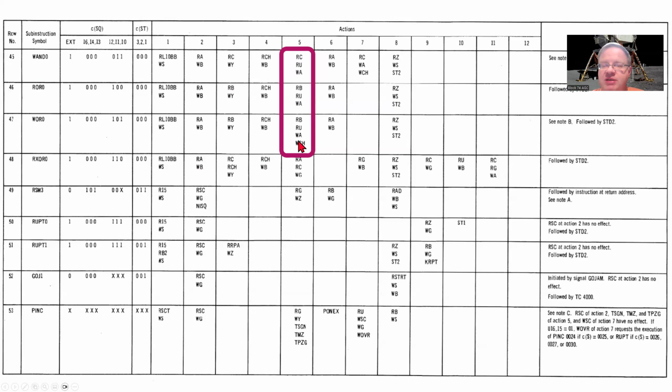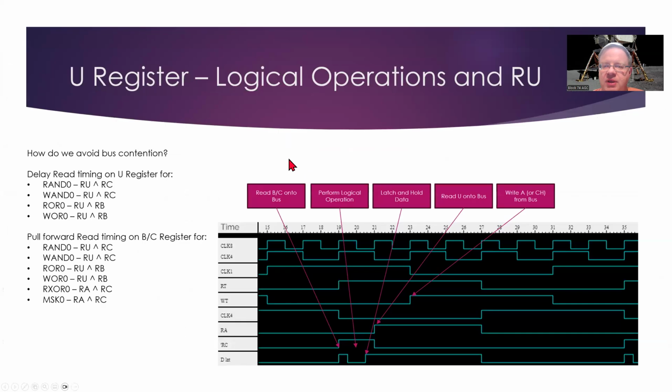So it simplifies things, in that the ALUs we use to perform these logical operations, like we did on the A register, don't have to perform different instructions. They can all be hard coded to pass everything through if we're not running one of these composite instructions, and if we are, then we can perform the logical OR.